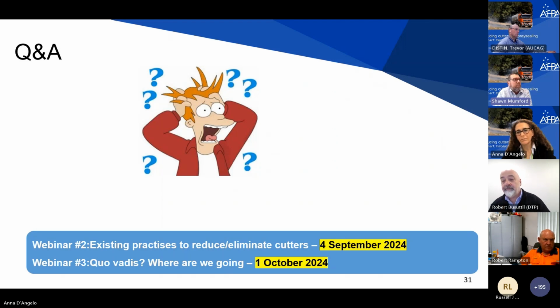So where I've seen them work successfully on a number of times, if you tried to lift up that seal, you're taking the pavement with you. And ultimately, the aim of priming the surface in the first place is really to make sure that you're getting good adherence to the seal that's following. So I think Robert's right. There's maybe still a little bit of work in some places to do with emulsion primes, but I do think that the ones that are available out there in a lot of places do work well.